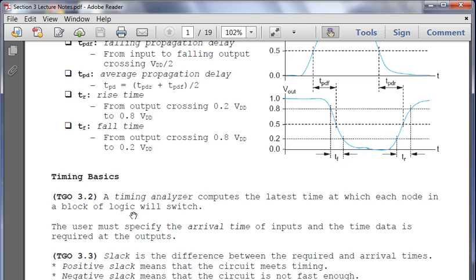You're doing an adder, for example, and you get the A input before you get your proper B input. Well, if you have 0, 0, and then suddenly you get a 1, you want to have 1 and 1, where you had 1 plus 0 for a while before you get 1 plus 1. So that can throw off your actual accuracy for a certain amount of time.